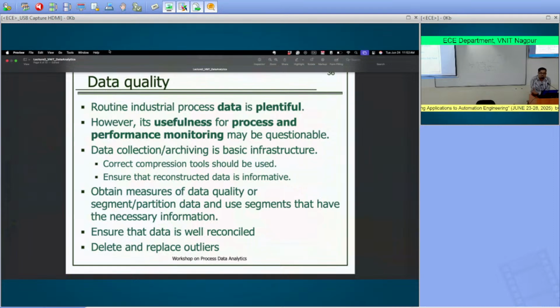Right, right. So there are specific industrial databases. They're made by Honeywell, a company called OSI Soft, Aspen Tech, lots of companies. And when you store data, you often compress the data because if you're collecting data every second, you're likely to fill up the space on your computers or servers very fast. So they compress the data. They only store data when the variable changes by a certain amount. Otherwise, they don't save. That's what the compression is. When you're collecting data, you can lose information if you don't compress the data properly.